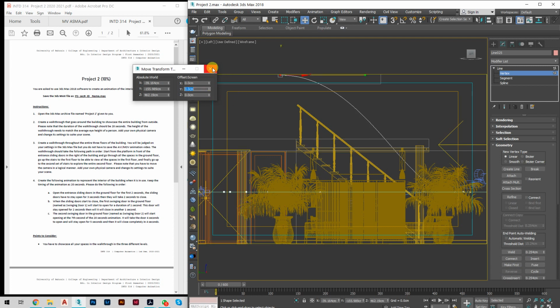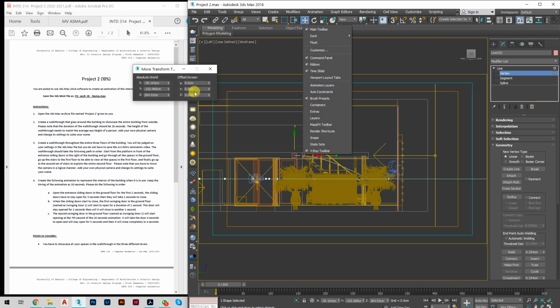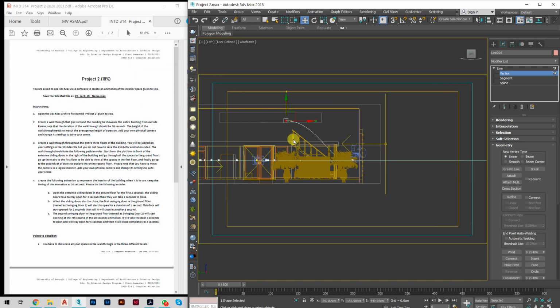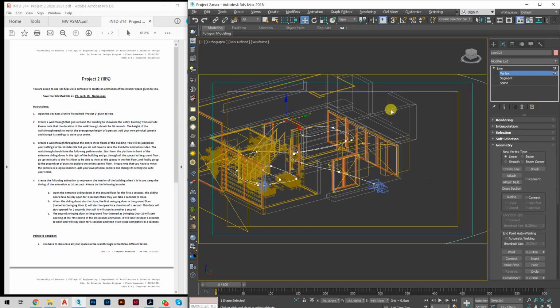So this means that the levels now are the same for the ground floor and for the top floor, or the first floor. Okay, so you can control it from here depending on the size. Again, you go here, right click and then 165. I think that the first floor is a bit lower than the ground floor. So later on when you're working, you can modify this. But for now, we'll keep it as it is.